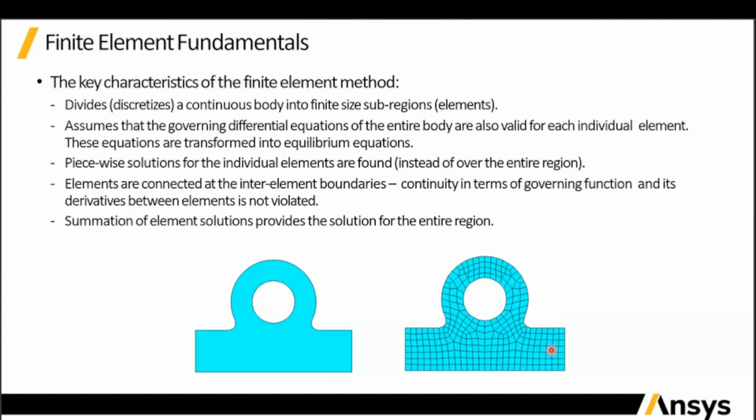Instead of solving the entire region at once, it first solves at the elemental level, and later integrates all the elements together. These elements are connected at the inter-element boundaries, so continuity in terms of the governing functions is not violated between the elements. Later, the summation of the element solutions provides the solution for the entire region.